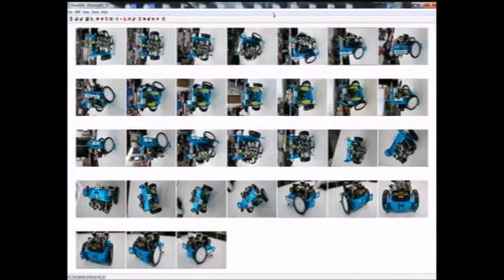So I was talking about there being a few unwritten rules about how to make this process work well. The key component is, since this is a purely optical process to acquire images, we need to have very even diffuse lighting. So even lighting all the way around to try and prevent as many shadows as possible will help the reconstruction algorithm create the shape.